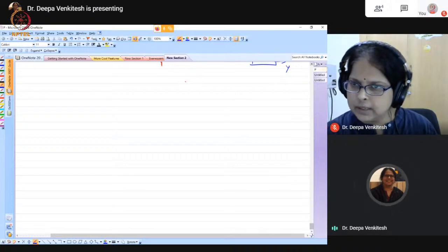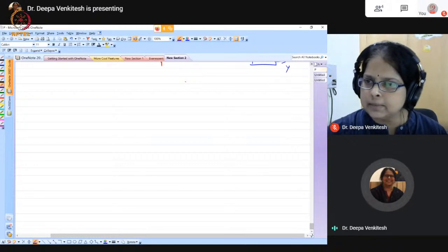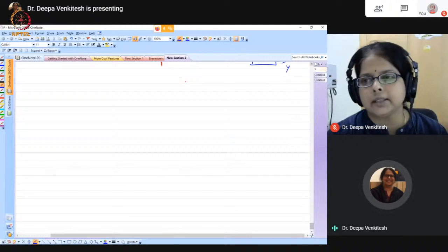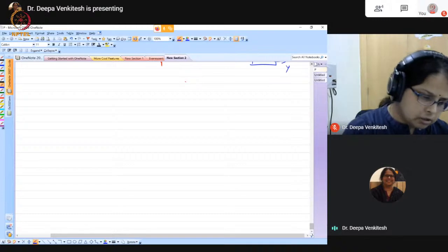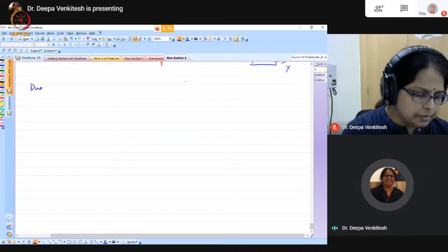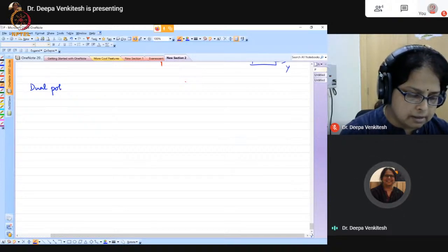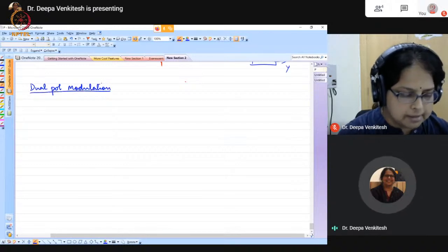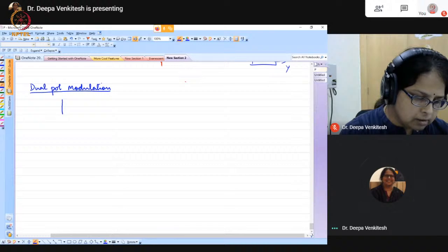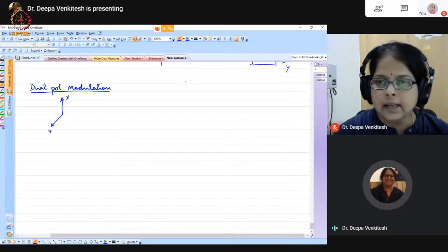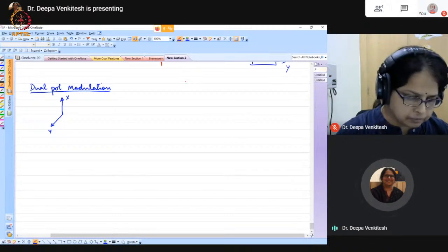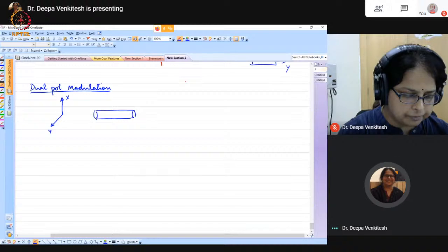Michael Jordan asks, how much polarization extinction ratio is acceptable at receiver side in dual polarization phase modulation system? This is actually an excellent question. So in a dual polarization modulation scenario, what really happens is you send, let's say, two orthogonal polarizations, data into orthogonal polarizations X and Y. That's what you plan to transmit through the fiber. It goes through the fiber.